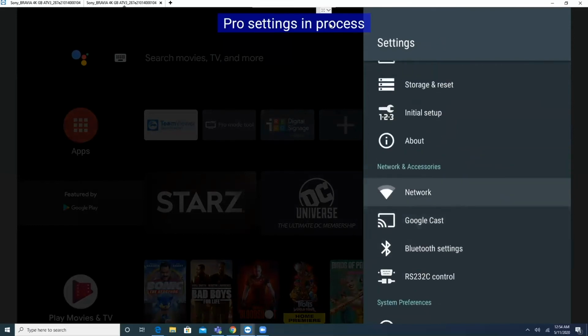Of course, writing your RS-232 code is a completely different animal. So we always advise you to use the BRAVIA Knowledge Center as your initial resource. If you are writing custom RS-232 controls, something special to our Sony Pro BRAVIA is that you have to set the standby enabled command. So if you have questions, feel free to reach out to your local sales support engineer, your account manager, your Sony rep.